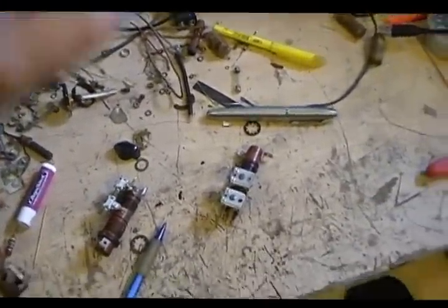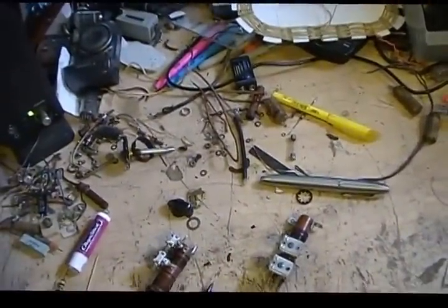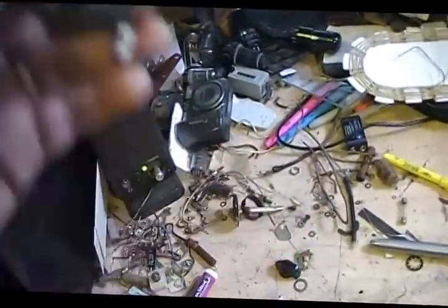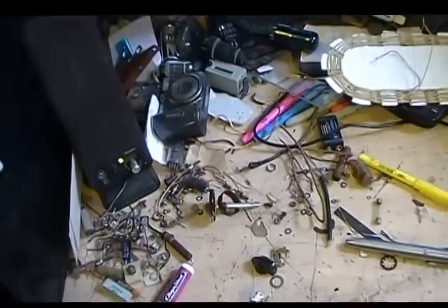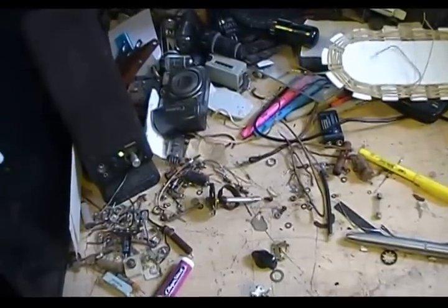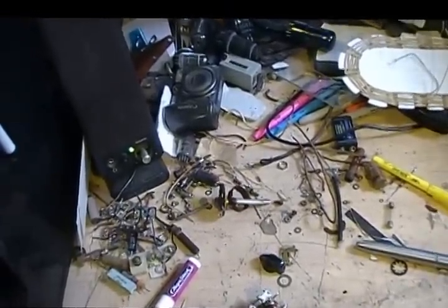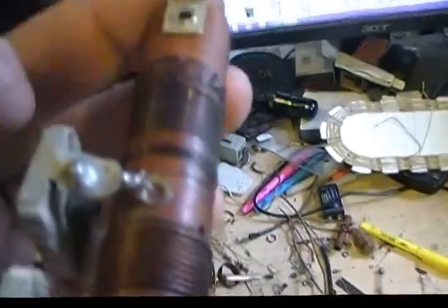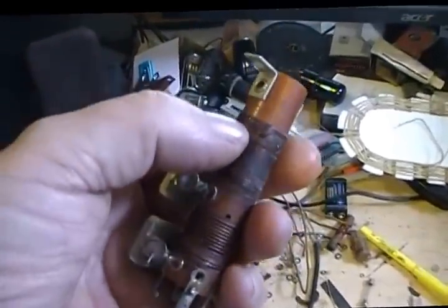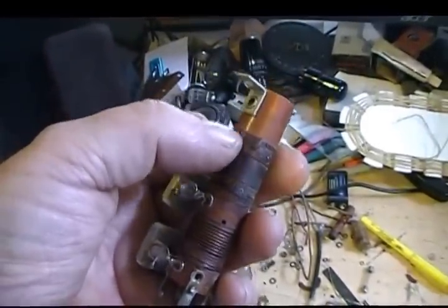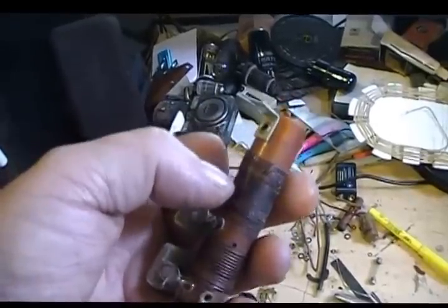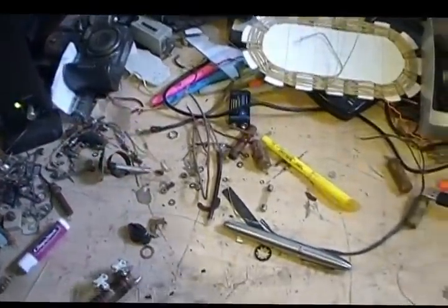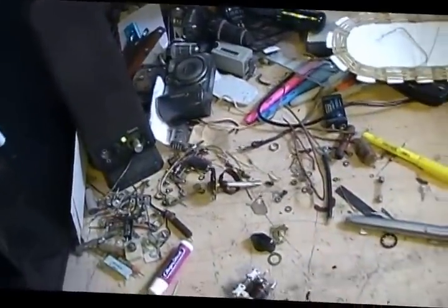But look for the common points. If there is no common points, if there's just individual connections, work with the oscillator first. Remember that tickler or primary coil has to be 180 degrees out of phase, which means the rotation of the wire will be different. In other words, your connections will be such that the rotations will be backwards to each other, the way you connect it up. So remember the 180 out of phase with the primary or the secondary of the coil.